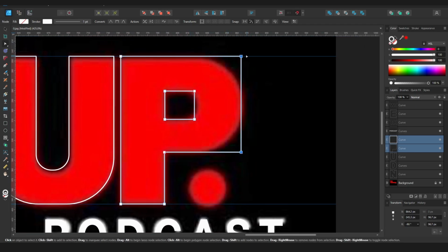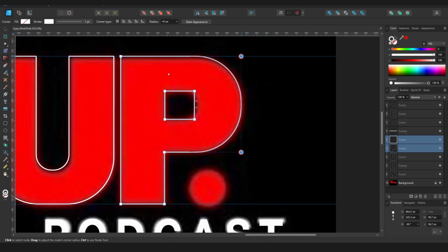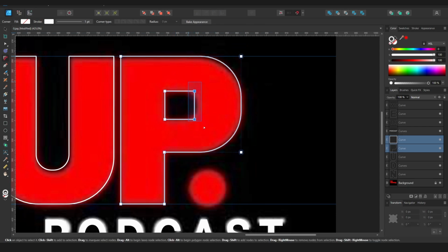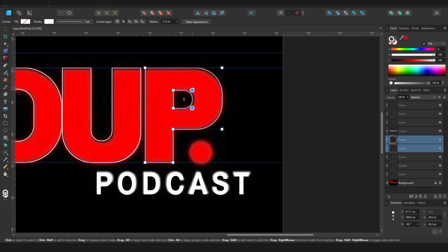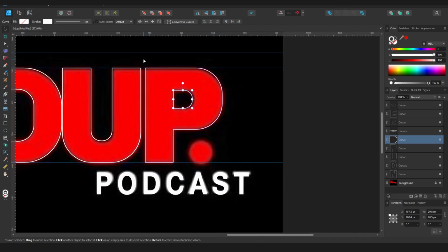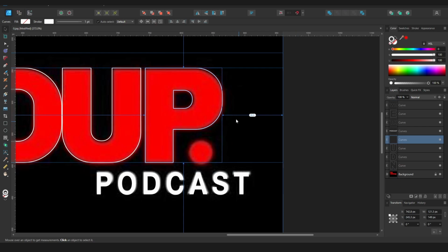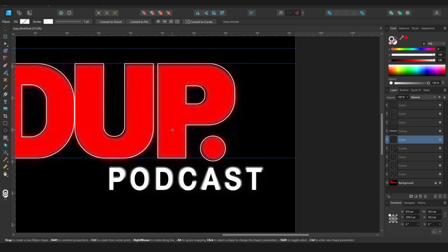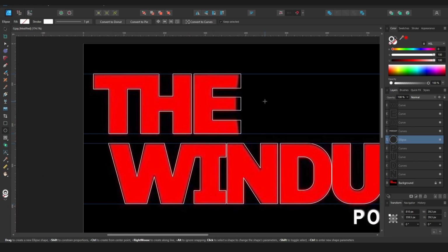All right, now we can grab these two edges, hit the C key, and fold that down or round that out, I guess. And then again here, round this out. And then we're going to hit the V key and select both of these, just like this, and hit subtract. And then the last thing we've got over here is this circle. Just try to get in the middle, hold down Control and Shift, and there we go. Close enough.